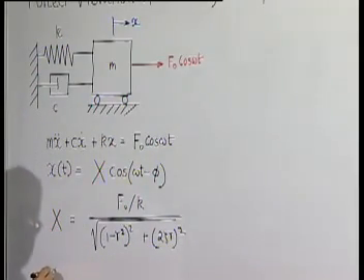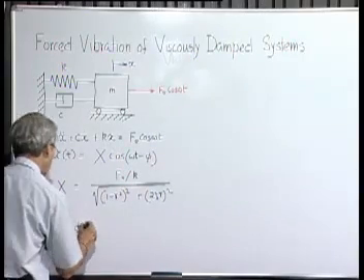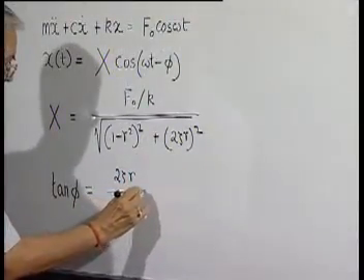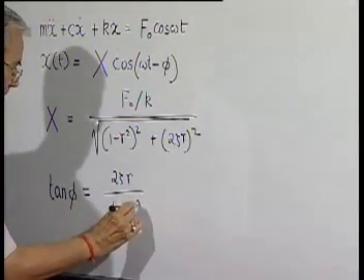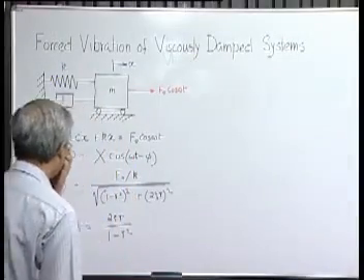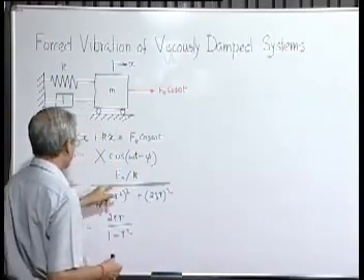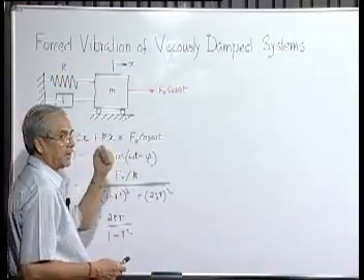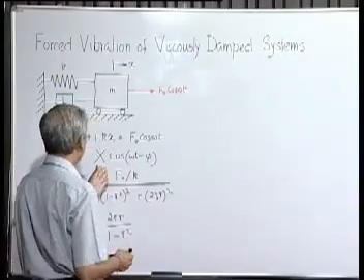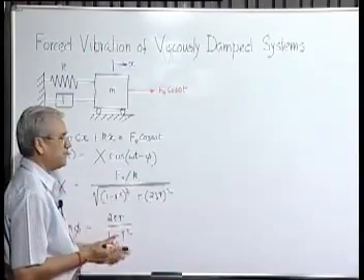and the phase difference, the tan of that. Then we notice that the static deflection when the same force is applied statically, that is F0 as a constant force, then the deflection of the system will be also a static deflection whose amount will be F0 by k.